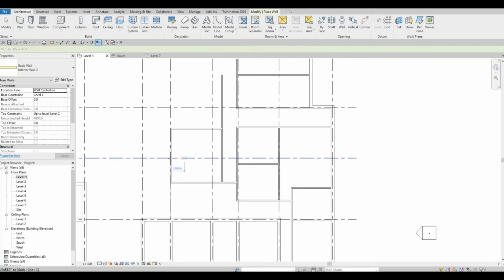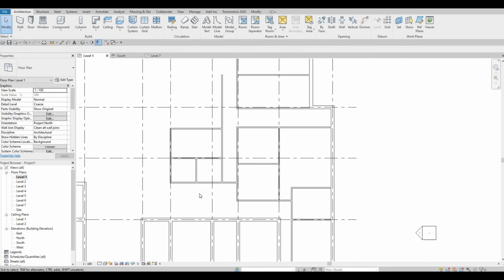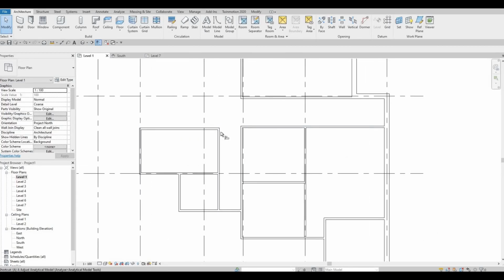And then the same wall, I'm gonna close this off. In the middle of this, select it and add in another wall, and then TR to trim this area. TR as well, this one, and then let's align everything else.